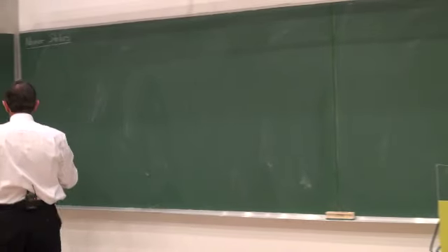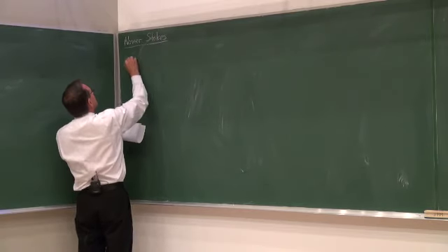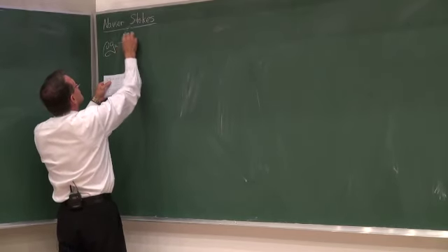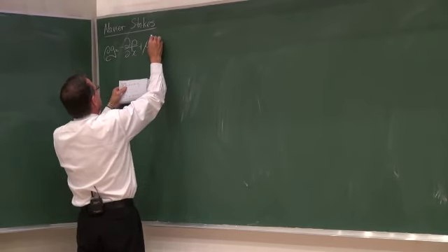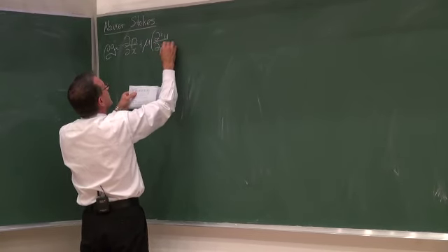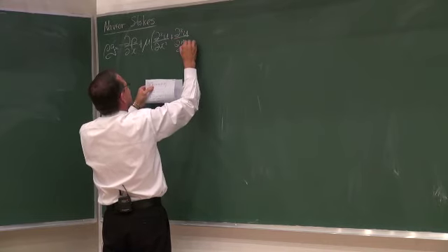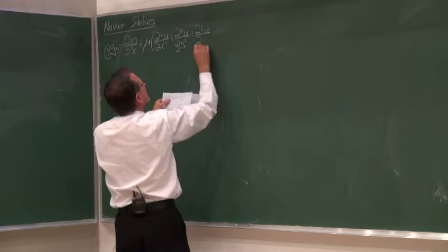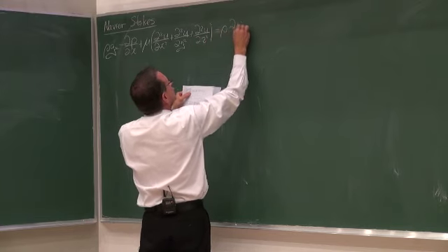Okay. Now, the Navier-Stokes equation, three components in a Cartesian coordinate system. Rho multiplied by gravity minus partial dp dx plus the viscosity multiplied by partial d2 u dx squared plus partial d2 u dy squared plus partial d2 u dz squared is equal to rho multiplied by du dt.